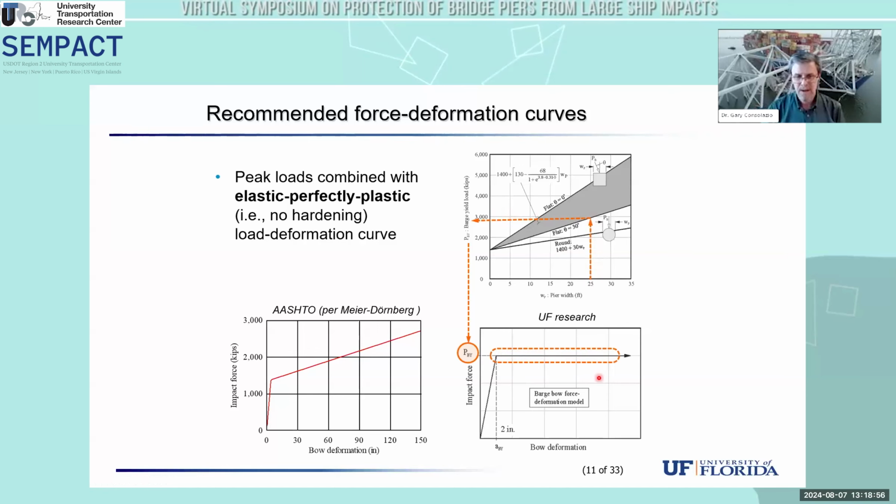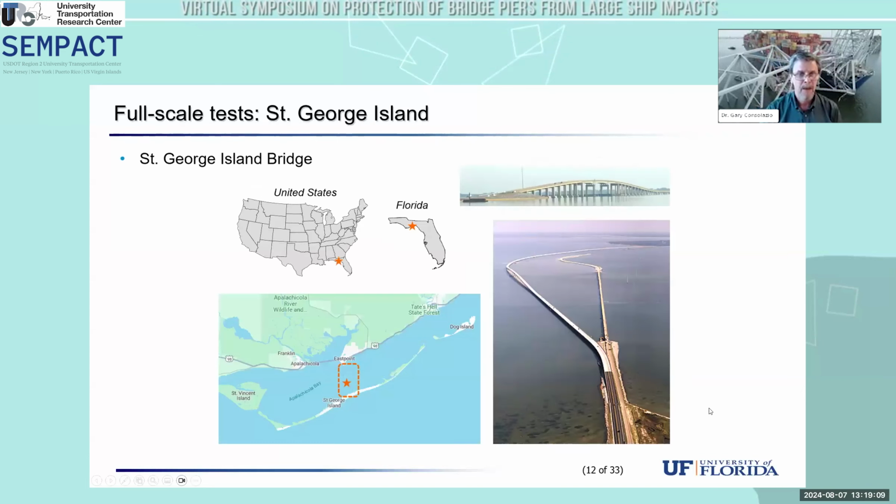These force deformation models then can be used either in equivalent static design, or what I would recommend is we use this in an efficient low-order dynamic analysis to more accurately capture dynamic phenomena, as I'll talk about as we go forward here. So this is all based on finite element modeling, and there's always a question as to the validity of finite element modeling. And so in the state of Florida, we've invested significant effort in physical testing, both at full scale and reduced scale, to develop confidence in the results from the FEA modeling.